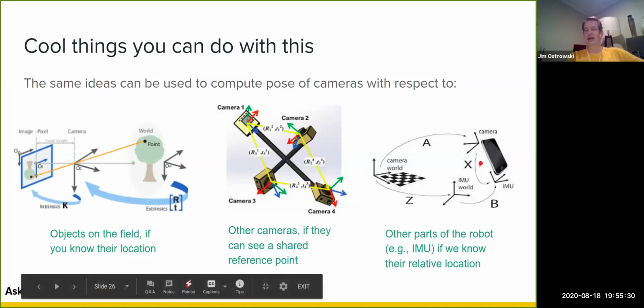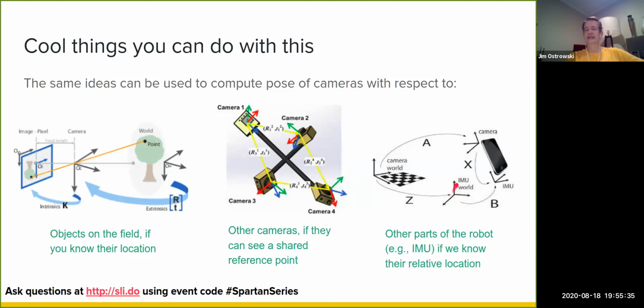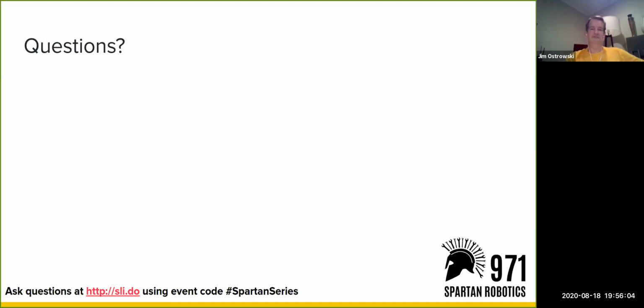And same thing if I want to just map a single camera view into, say, where the robot origin is or the IMU is, I can do that. And there's some really cool stuff that, again, hopefully we'll be able to talk about next year. There's another routine called Kalibr that takes IMU data and camera data and fuses them together to compute the extrinsic calibration, to figure out where the camera is relative to the IMU and so the robot reference frame.